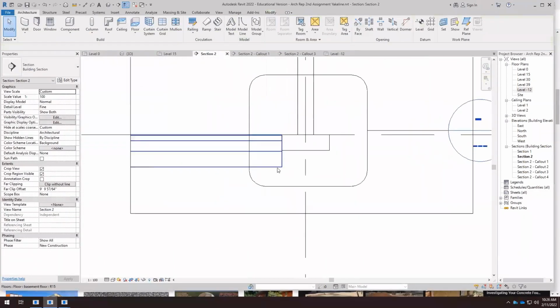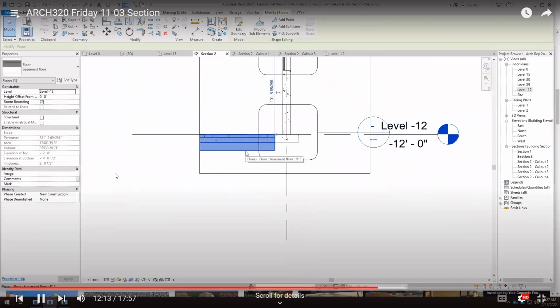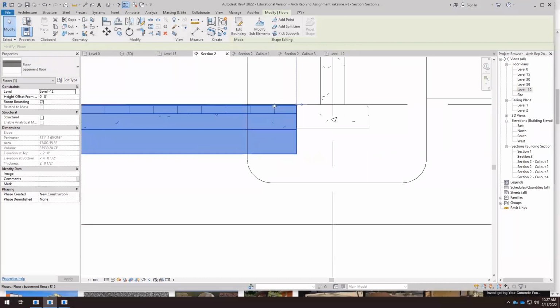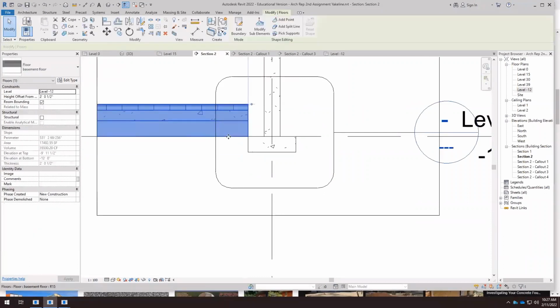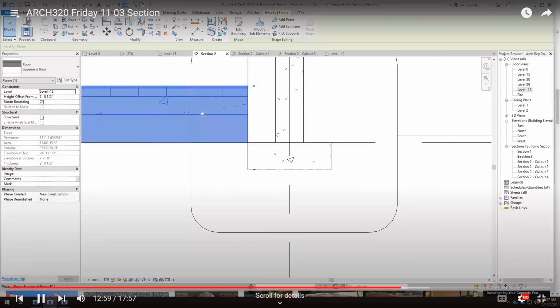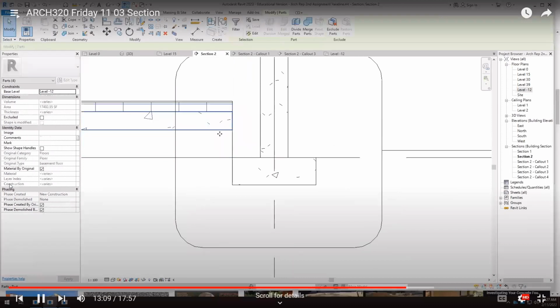And now there's a floor, but the position is not the right one. So we need an offset. Okay, so we need a height offset, and if it's a 2.6-foot floor, we have to move it 2 feet up. So let's change this height offset, 2 feet, 2.5, sorry, and that's it. And now those are different layers, but we have to create parts.